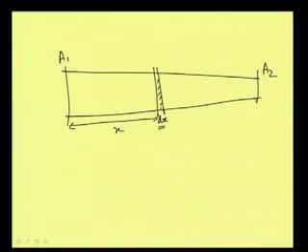But the L, what is that? L will be dx here, and the velocity of course we will have to take based on the area ratio. Then, with the friction characteristic f, we can find this value, and finally to get the total head loss we need to integrate it from this area to that area, and then we will get the head loss in this sort of pipe.